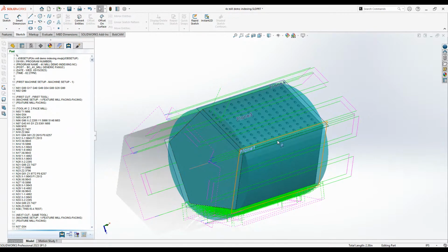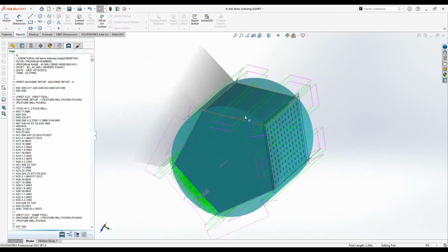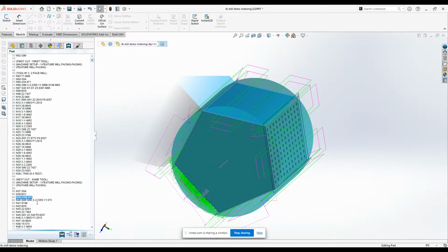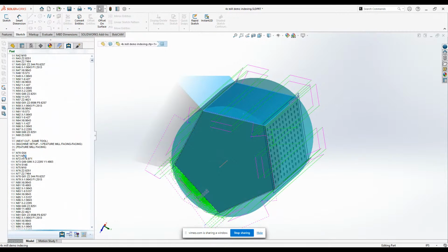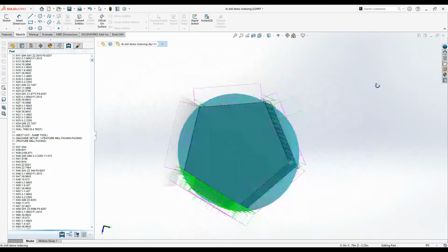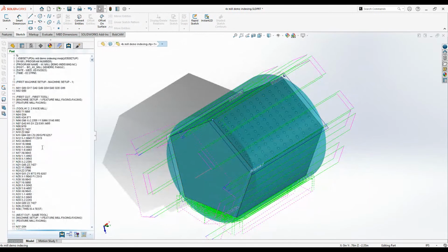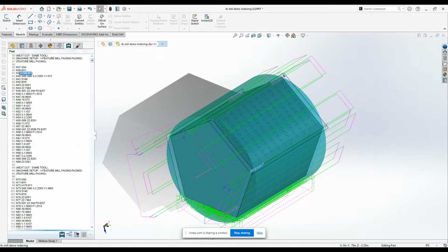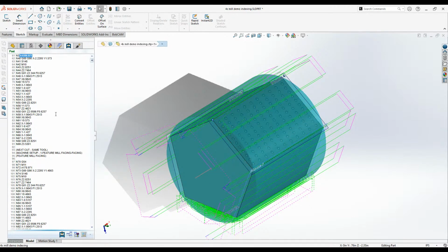As Al mentioned earlier, we could start with our machine setup pointed at the first face here, and then we could do A0, and then it would be a little easier to determine A0, then A72, and then A144 here. But since we started with the z-axis pointed to this peak here, it's actually just going to rotate forward to A34 and then A106 for the next surface.